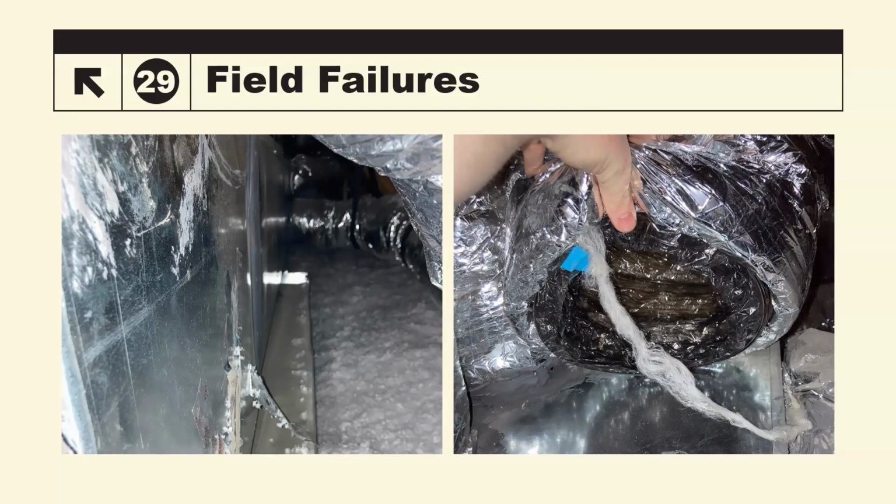But a lot of times those ducts might be sitting on there to where if you just look at that system and you glance at it, it looks like everything is set in there like it should be. And then ironically, it is not. And it's not going to pass the duct test because it's not even attached to the system. So that's one of those things where just giving them a little tug while you're on the service deck and you're in the attic would be a good idea.